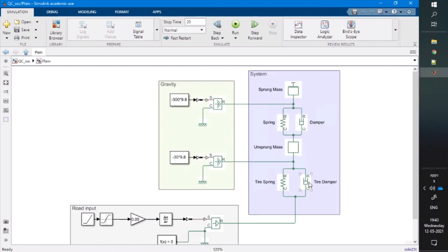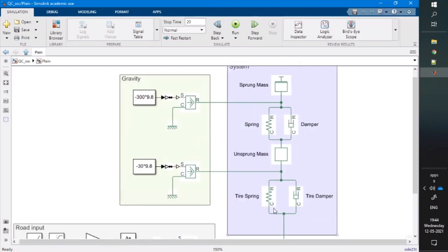What we care about from the user side is only the schematic diagram. If you are bored or lazy to derive the equations of your system, Simscape is there to help us. The arrangement is very simple: you have two systems of springs and dampers and two masses, connected one to the other.